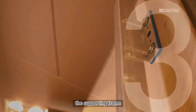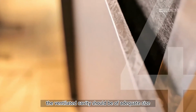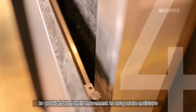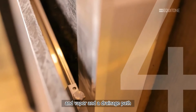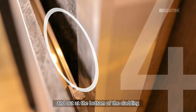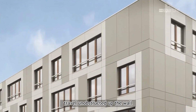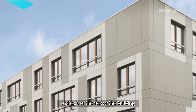The supporting frame should be designed to carry the panels and a certain amount of wind loading. This supporting frame is commonly of aluminium, galvanized steel or timber battens. The ventilated cavity should be of adequate size to provide both air movement to evaporate moisture and vapour and a drainage path for water to run down the rear of the panels and out at the bottom of the cladding. Air must be allowed to enter at the base, travel unobstructed up the wall and exit at the top of the building. Now for the physics bit.